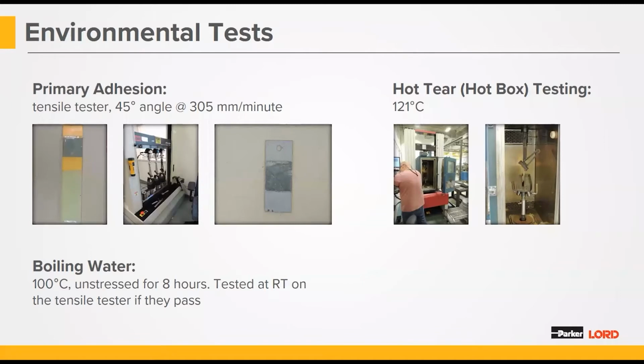For boiling water, we used 100 degrees C water, unstressed for 8 hours, tested at RT on the tensile tester if they pass. In addition, we did hot tear testing on a hot box at 121 degrees C.